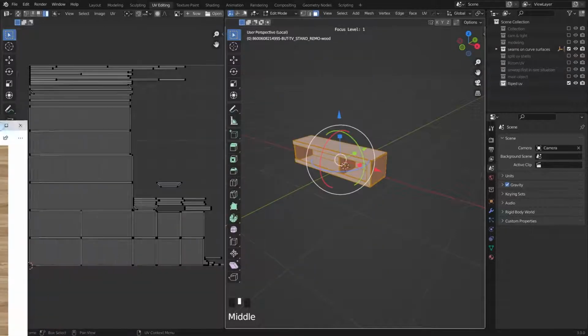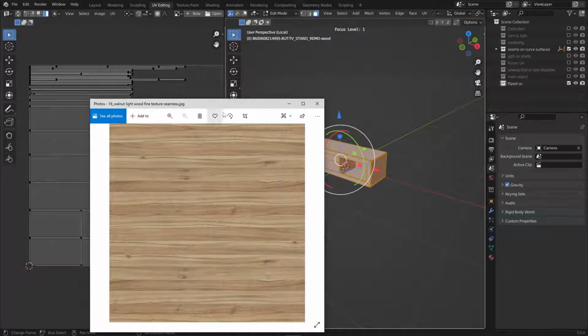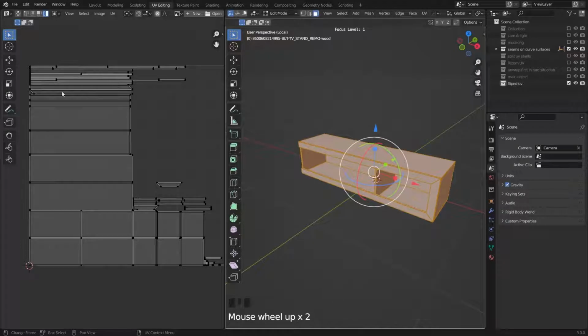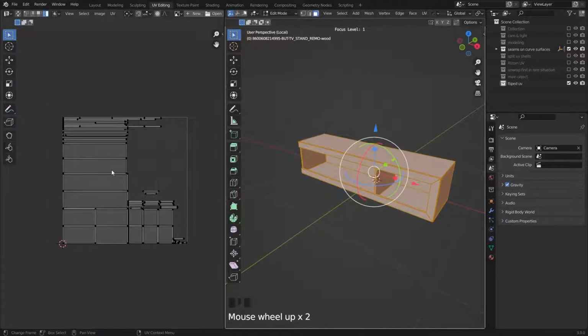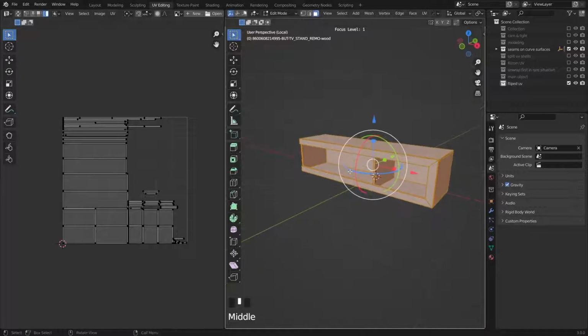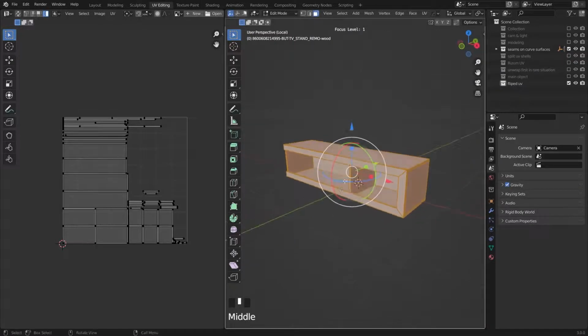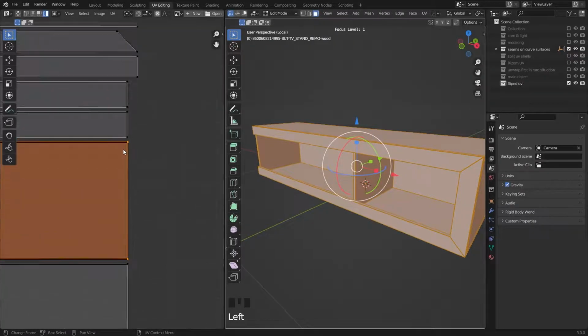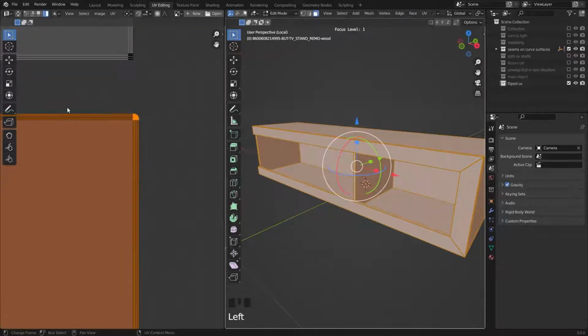So, based on these textures and your material, your UV shells should have the correct rotation. As you can see, I put all my UV shells in horizontal rotation and it works. You should always check your UVs. But the important thing is, the rotation should be completely organized.